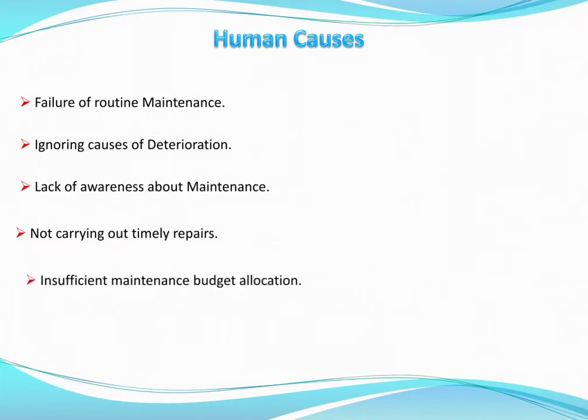The next is insufficient maintenance budget. We never have something called a maintenance budget. Fine, now that concept is coming up, but in our residences, apartments or societies, the fund called maintenance is only used for paying the watchmen, clearing the electricity bills and maintaining the lift. Cleaning, painting and doing minor repairs are not given due consideration, and this becomes the most important factor for deterioration of the structure.